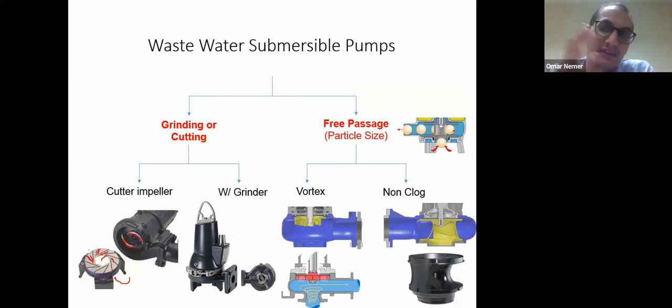So as you can see, cutter impeller. So you can see mainly who's doing the cutting here is the impeller. That's the difference between these two types. Now, usually, again, as a general view, the non-clog has the biggest efficiency among all types. Now, if I want to pump various particles without any risk of clogging, you can go with the vortex.